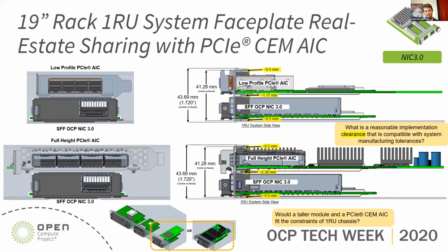With the NIC form factors over and under, they're both front faceplate pluggable potentially, whereas with a PCIe add-in card form factor, the PCIe add-in card is already set, reserving real estate within the system itself, while the OCP NIC form factor is still serviceable and hot swappable from the faceplate.